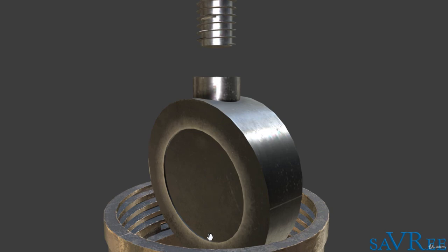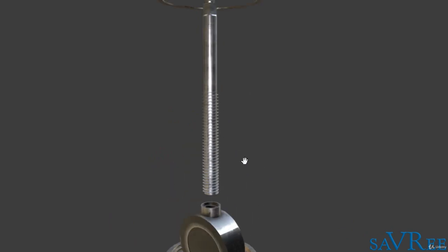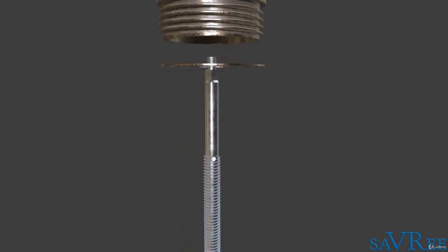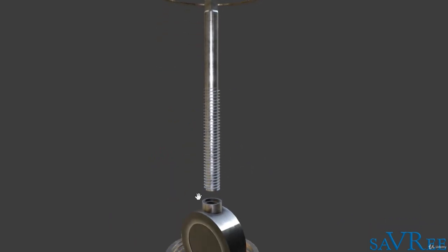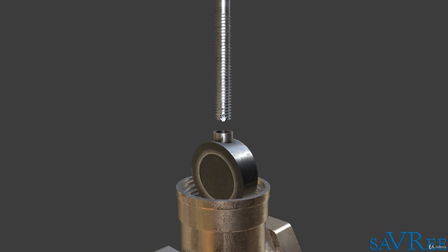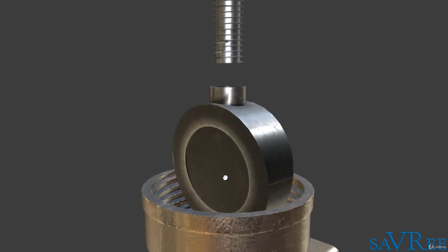As it screws into the disc, the disc is going to be pulled up the stem. As it's pulled up the stem, we're going to open the valve. So rather than having a rising stem, we're going to have a non-rising stem, because this is just going to turn, and as it turns, the disc will move from here, the bottom part of the stem, and it's going to be dragged upwards, obviously, until it reaches the top of the stem.